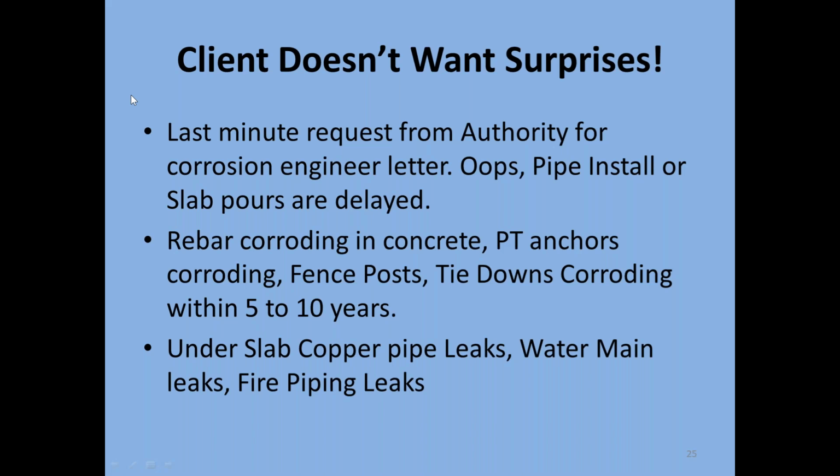Other surprises are the rebar corroding in the concrete much faster than anticipated, the post-tensioning anchors corroding, fence posts corroding, tie downs corroding within 5 to 10 years. All of this happens, so these are the surprises that you can avoid by just doing the homework of a corrosion study first. And that's why we recommend testing those 8 different factors.